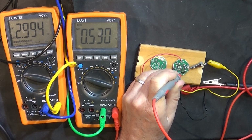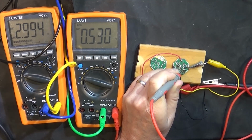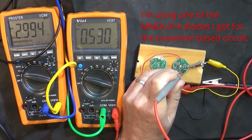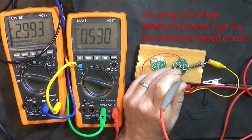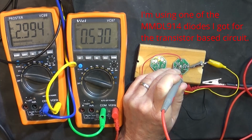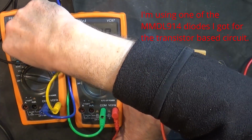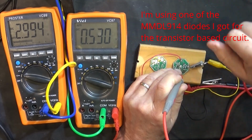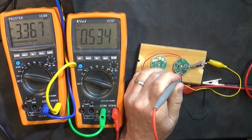Okay, so I've got my diode in. Not without a struggle, because there's a very faint line marking the end, and once you've soldered it and got some flux over the top of it, you can't see it. So I've got it in the wrong way around first attempt. Anyway, she's working now, and rather than try and point the camera at the power supply, I've got 2 meters going here. So that's 3 volts in and 0.53 volts across our diode. Okay, so we wind it up to 6 at the other end of our range.